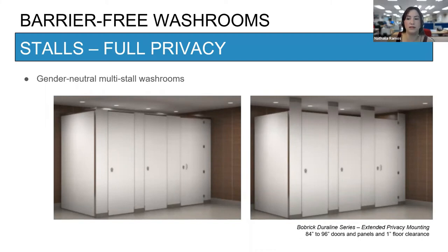Multi-stall washrooms are a basic health and accessibility requirement of a building and should be designed for all individuals. Typically, multi-stall washrooms are gender specific in staff and public areas. However, in high-use public facilities, gender-neutral multi-stall washrooms may be appropriate because they allow an individual providing assistance, such as a parent or a caregiver, to go inside the stall without feeling awkward or discriminated against.